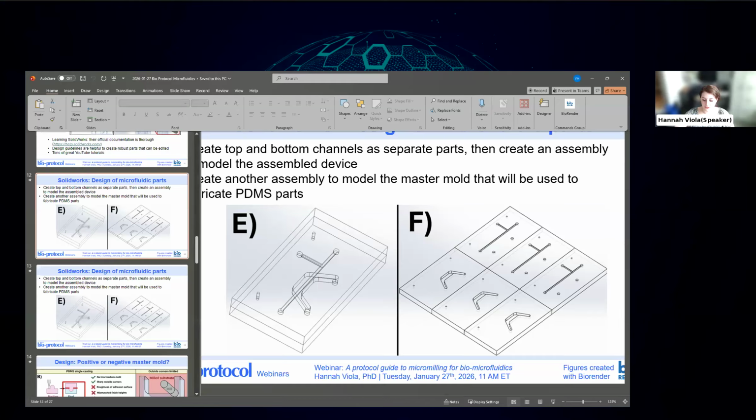And if you're doing 3D features, you have to consider that. How are the molds aligned? In what I ended up publishing, I added the alignment indicators here. So on the top and bottom, I put just a little button. But when I actually made them in grad school, it didn't occur to me that I could do this. So I just did it by hand in approximately the same spot every time. But I recommend putting some kind of indicator.